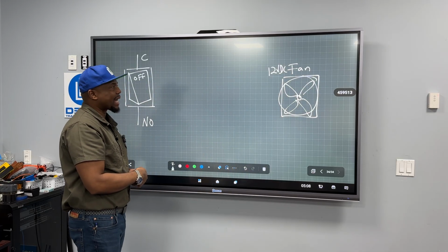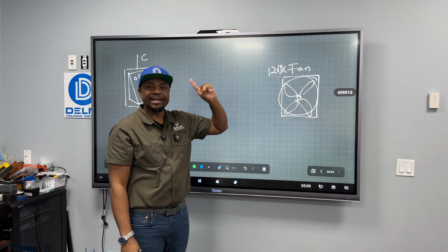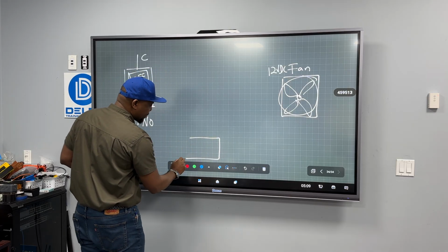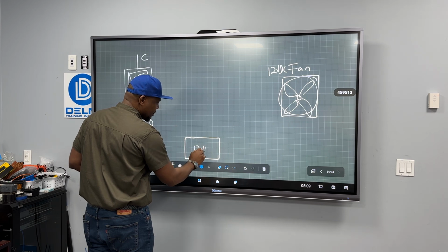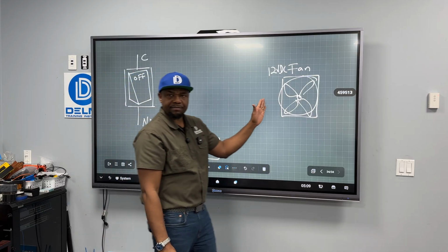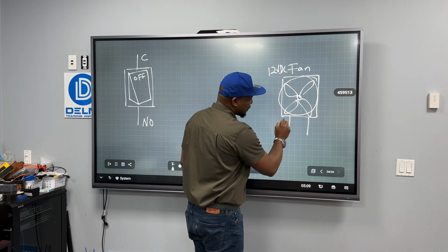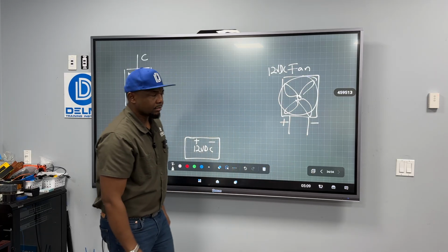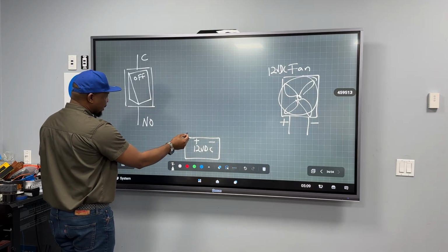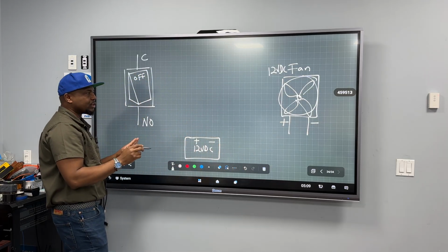Then definitely what I can do in basic terms is I need a power supply that is going to be 12 volts DC. So I find a 12 volts power supply, and this is positive and negative, right? With the output device, anytime you see an output device, you're going to have two terminals, a positive and a negative. So how do I connect this? I want this positive voltage to go through this circuit and come back home. That's just what I want to do.